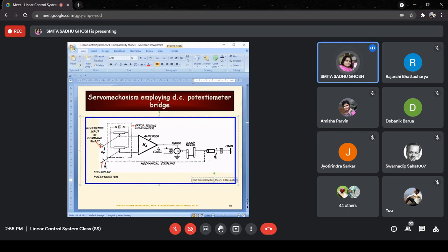It's going to be either in degrees or in radians, theta r. Now this element is connected and acting as feedback. More about that in a moment. If we look at the output of this element, we find that it is going to be a voltage which has been generated and that is proportional to theta r minus theta c. So that voltage is being applied at the input of this amplifier, an op amp maybe.